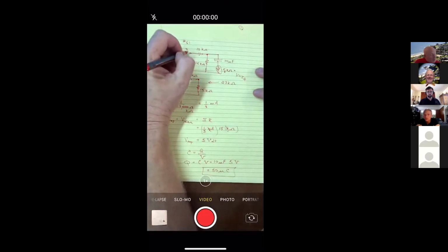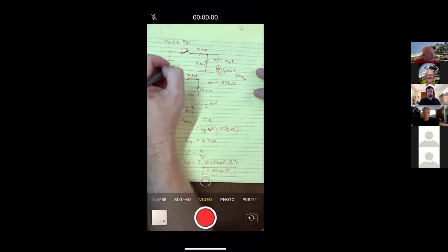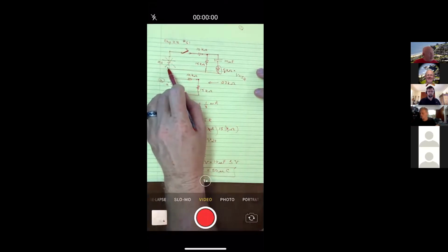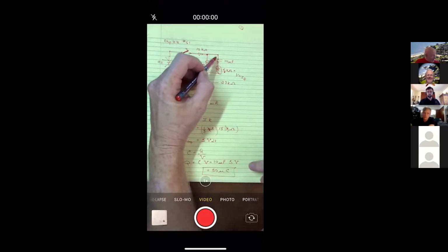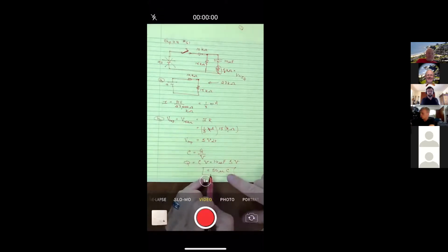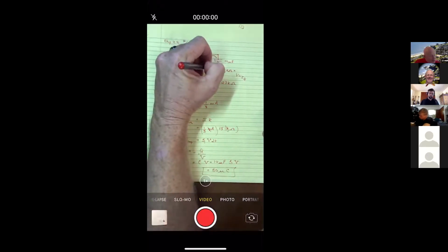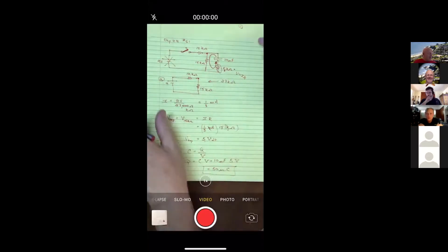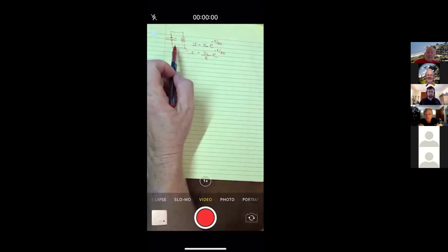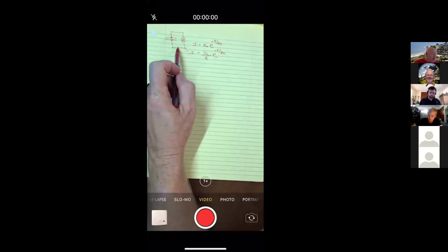When you open this switch, you are not going to get any more current from this battery. What's going to happen then is this capacitor, which we have said has been charged up to 5 volts or 50 microcoulombs, is now going to discharge itself, and that's going to be exactly like this problem, where we have a charged capacitor, and now it discharges.